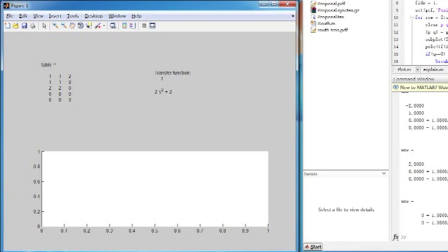Thus, Routh-Hurwitz maintains the information of stability of the system by sending the poles off to infinity one by one, while keeping track of which side of the plane they went off to by the change of signs. But when should we terminate? Obviously, we terminate at the end of the table.